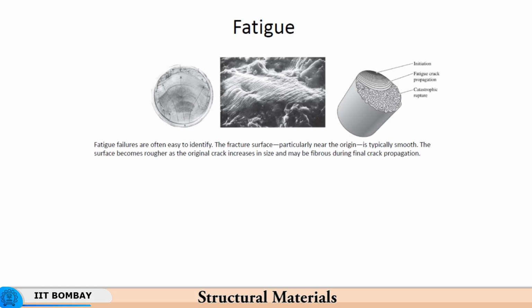Like in the case of a boiler, your circumferential stress, for example, might reach a certain value when it is under operation, then it comes down to 0. Again it goes to 100 MPa or whatever stress it might be, and then it comes down to 0. So this way the stress in fatigue loading reaches a certain level and then gets relaxed.